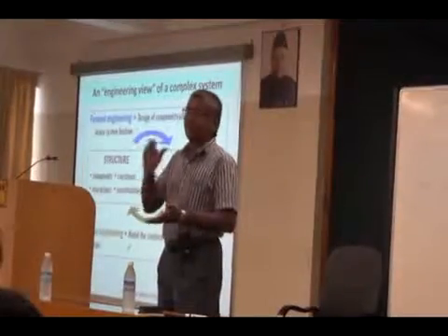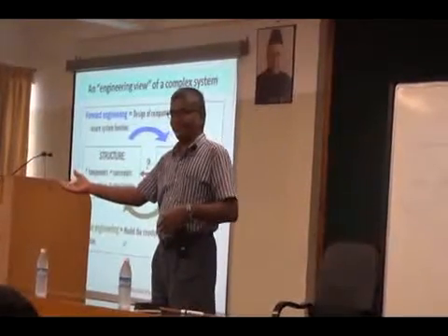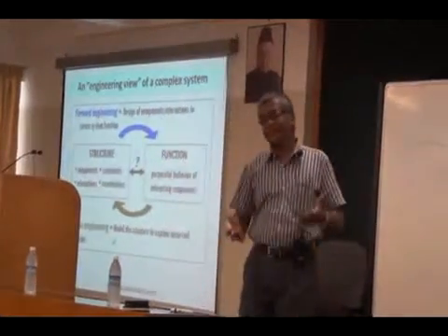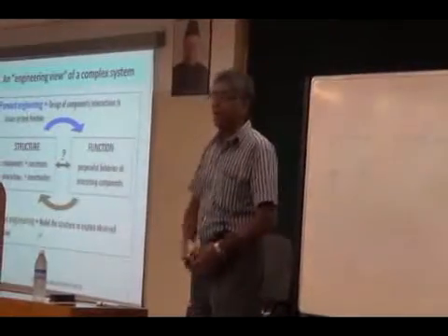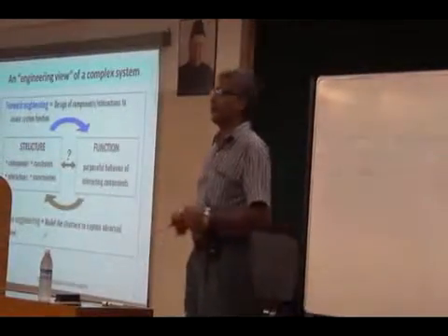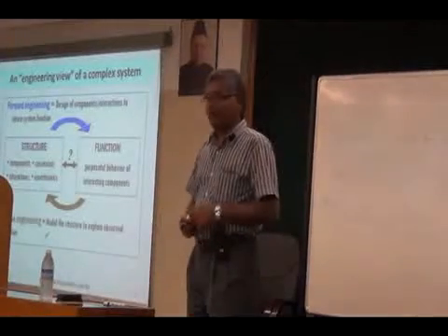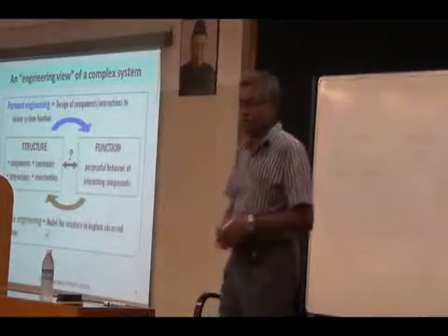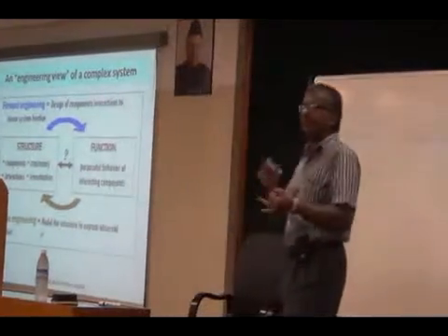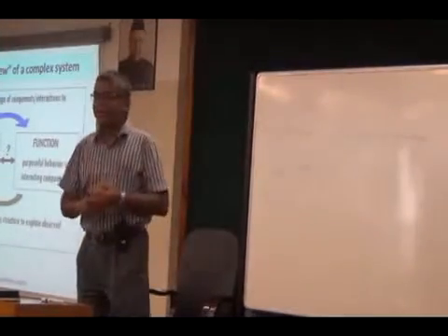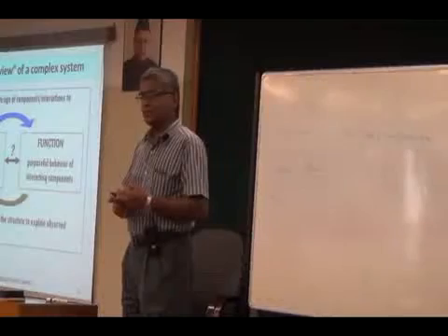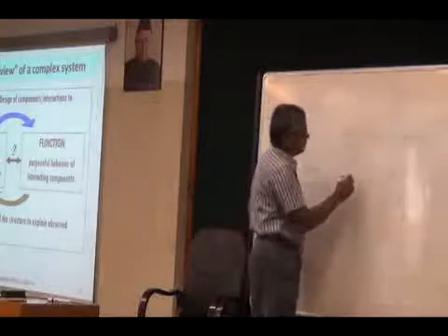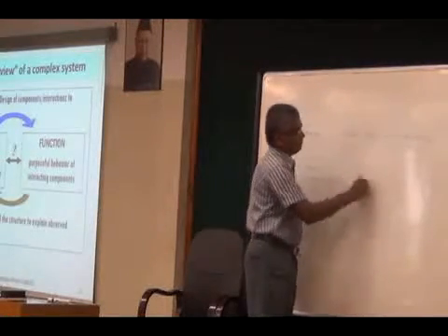So we have customer requirement, we have market requirement. What is my competitor doing? Then there is a government regulation or law. What should be the specifications in your bike? What kind of safety features are okay? So this we call regulatory requirements. And there is an environmental requirement. This should be the pollution level, this should be the NOx, this should be the soot allowed. So I have customer requirements, market requirements, government legal or regulatory requirements, and environmental requirements. All put together, all this becomes my PDS, product design specification.